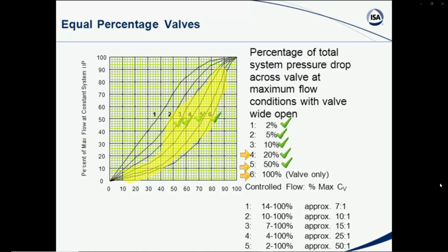And valves you do not want to have operating below 10% open because you get down too near the seat shut off.